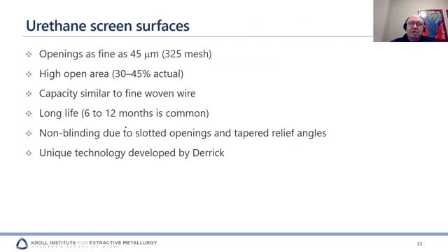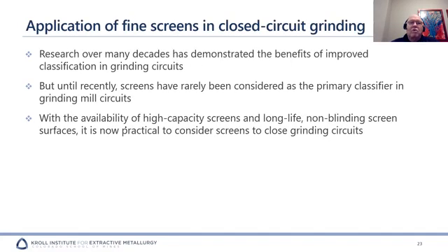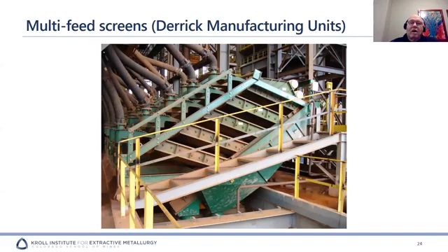Urethane screens, like I said, are becoming very important and being used a lot more. In grinding circuits, if you have a hydrocyclone, you'll end up with misplaced material. Remember I said there were gravity issues. You'll get coarse material, and fine heavies coming to the cyclone underflow because of their heavy specific gravity. You don't necessarily get a particle size cut. And so this is a stack sizer.